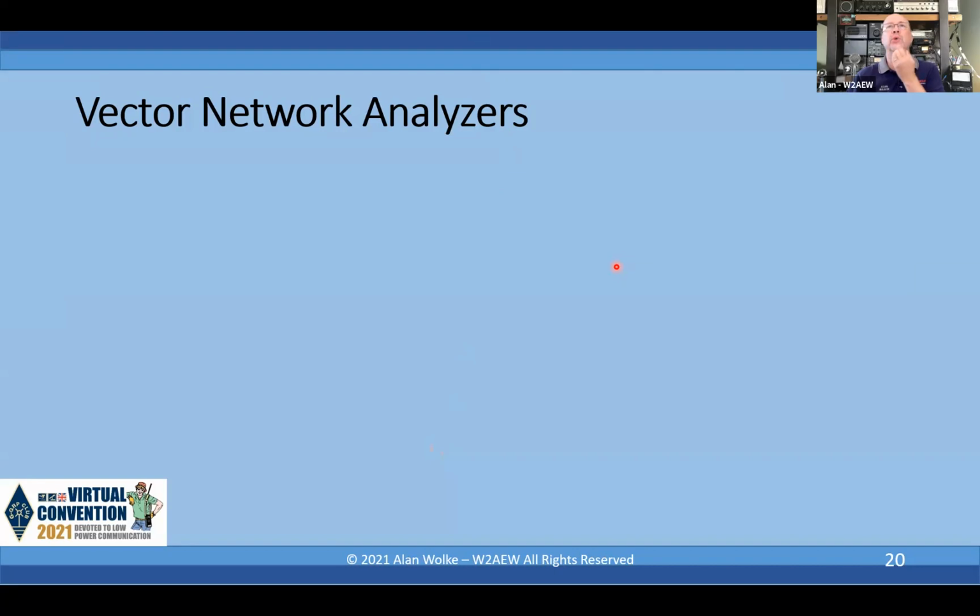Yeah, I just pulled the questions up here so I can see them. Okay. So David's question: can you use an IC-7300 as a spectrum analyzer? In a sense, yes, but you want to be careful with that. It does have the spectrum display and the pan adapter. I don't have a 7300, so I don't know how adjustable that is in terms of frequency range or span and how accurate it is. But if you're just looking at spectral content, that's essentially what the pan adapter is. But you have to be careful about how much power you put into it, because a radio receiver is generally not going to be designed to handle the higher level powers that a spectrum analyzer could.